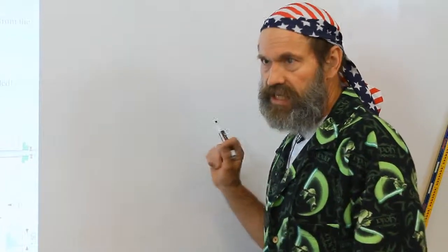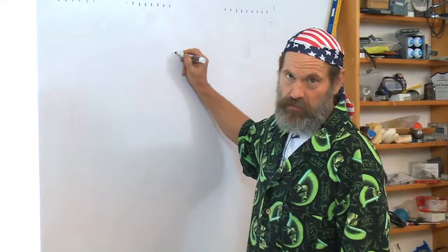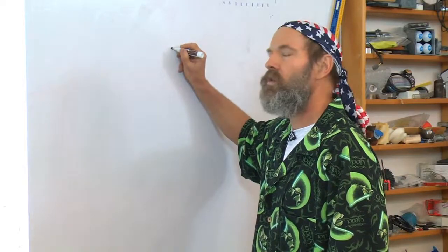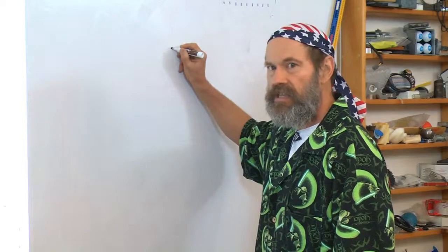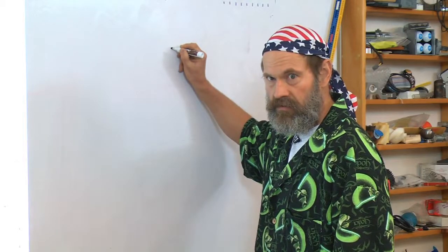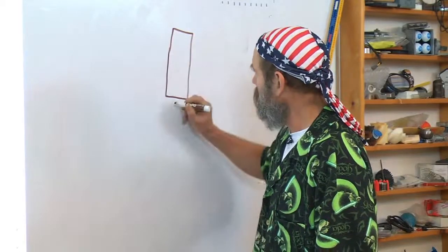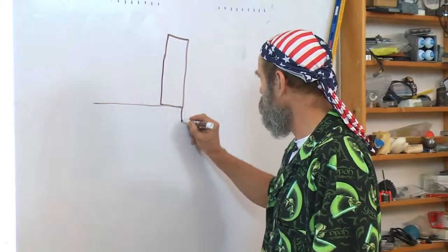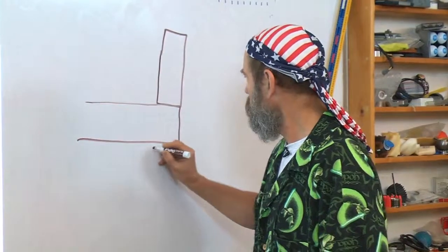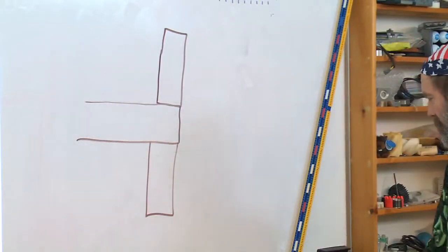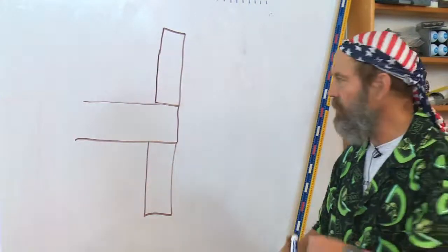She knows St. Venant's principle. And how does it apply here? What am I going to draw next? Think ahead to what's happening. Where does this come from? Here's the wheel, the shaft. And how do I know where to put the bearings? 3 to 5 diameters away.